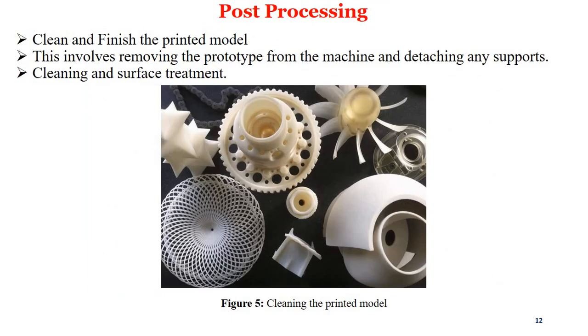Post-processing. In this process, we have to clean or finish our printed model. We remove the support structure and remove some extra material by detaching any support. After that, we clean it and do surface treatment.